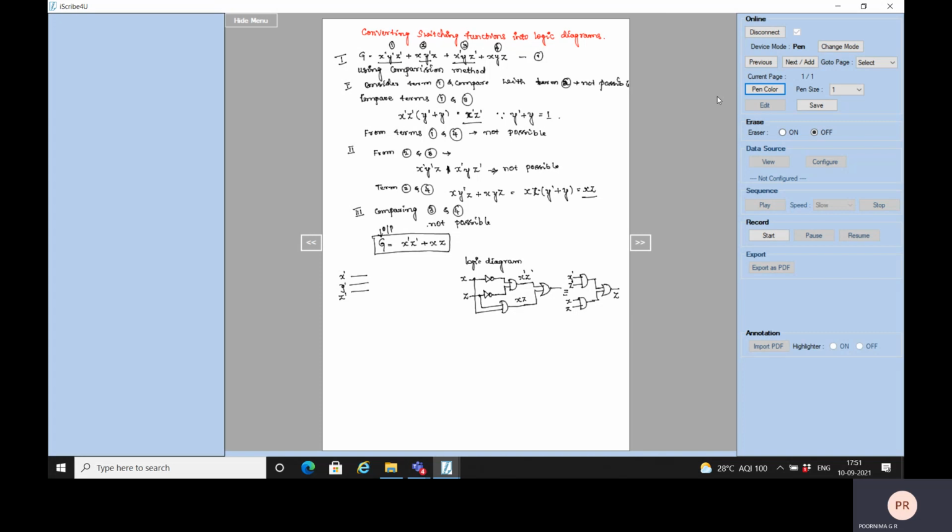So that is this equation 1. For equation 1, a logic diagram is constructed with X bar, Y bar, Z bar, AND, because that is a product term, or because X, Y, Z are only three variables, you can term this also a min term. The next product term is X, Y bar, Z,